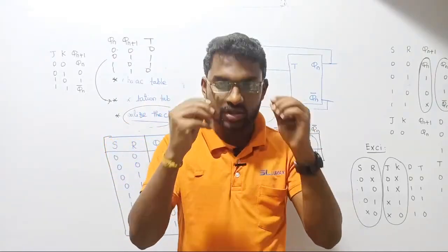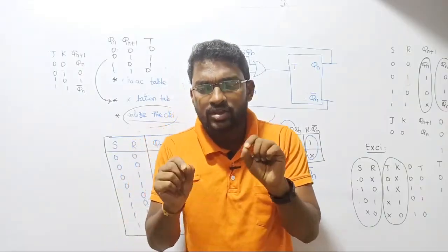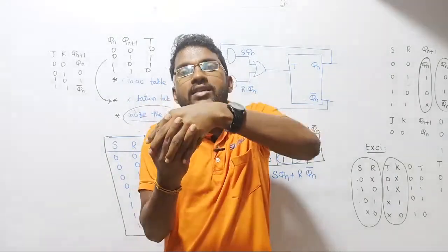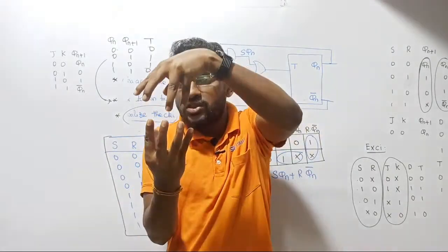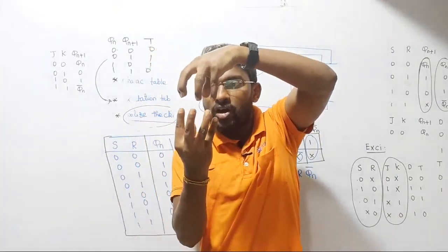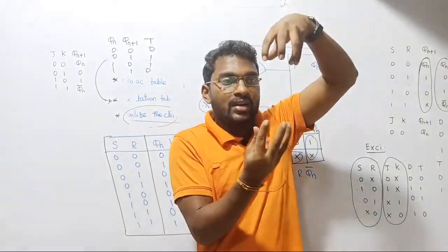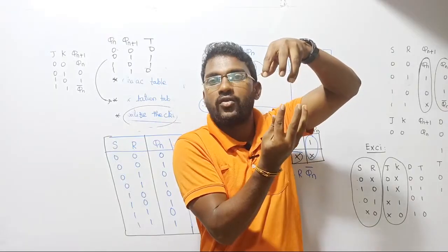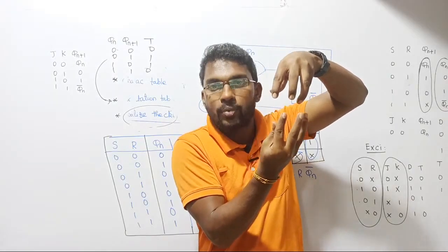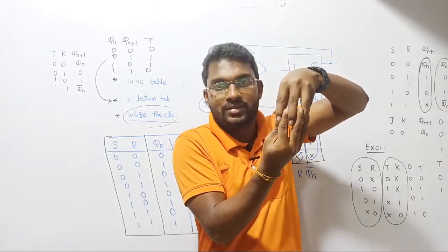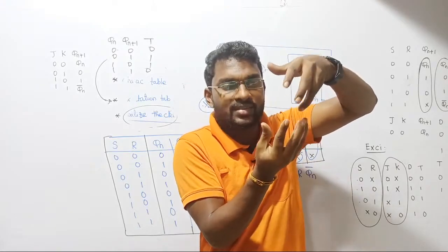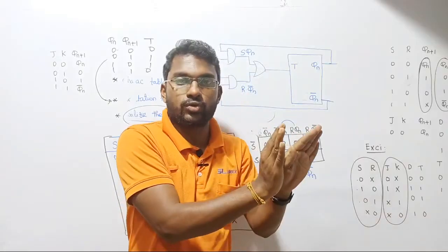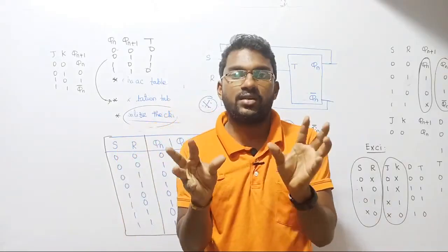So coming to the conclusion here, what do we mean by synchronization and asynchronization? Synchronization means everything is synchronized together. In a synchronous machine, the rotating magnetic field and rotor are synchronized. Whereas in an asynchronous machine, the rotating magnetic field and rotor are not synchronized together. They are rotating at different speeds. We have the term called slip in the induction machine, whether single-phase or three-phase. Do you all agree with me? Fine. That is the meaning of synchronization and asynchronization.